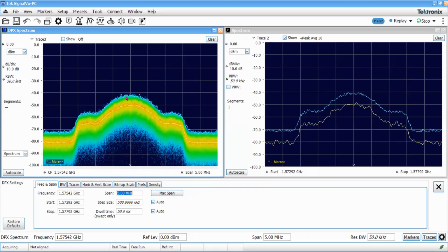So this is a 2 megahertz main lobe. Then we have the side lobe. We call them the main lobe and the side lobe. This main lobe will have more than 90% of the power transmitted from the satellite. For GPS L1 C/A, this bandwidth, the PRN code bandwidth, is 2 megahertz. When you design the receiver, your receiver bandwidth must be larger than this to get all the power transmitted by the satellite.